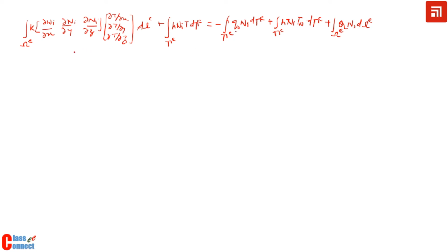So now this is our main equation that we can focus on and try to expand in the form of finite element formulation. So let us take this first term, and remember my basic expression of the field variable, that is how I have assumed my field variable for the case when I assume n is equal to 8, that is an 8 noded brick element.